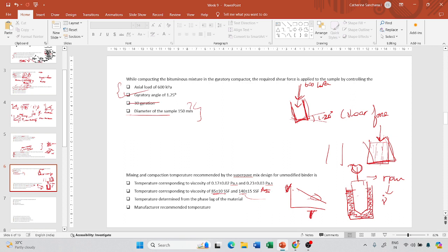And if the viscosity of the material is less, then obviously there's not going to be any drag here, right? So a lesser torque is sufficient, okay? So from this torque which is required to rotate the spindle, you can measure the shear stress, and from the shear stress and shear rate you can find out the viscosity.